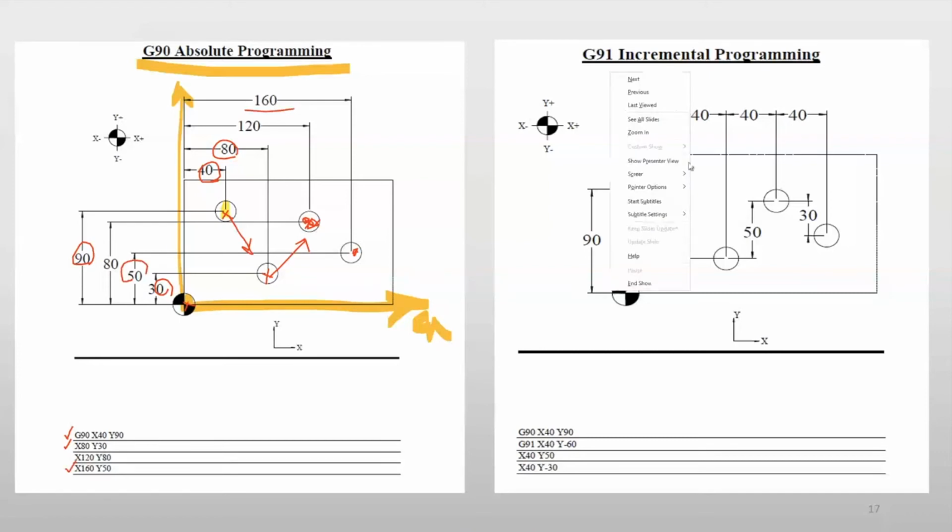However, the developers came up with a new language which was added later. It's the G91. It's incremental. And I will tell you why and when they did it. Incremental remembers the position it has. So you're expanding the memory. And there are benefits of using the incremental tool.